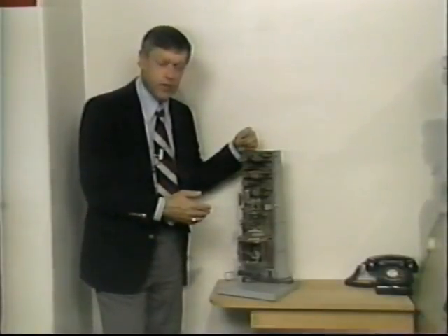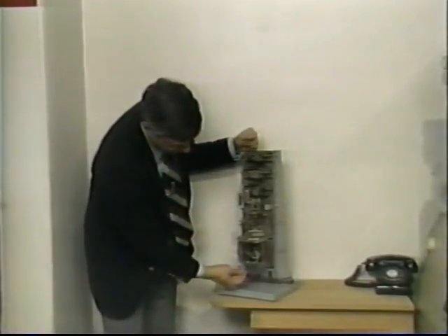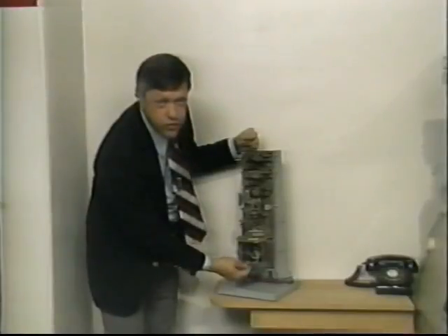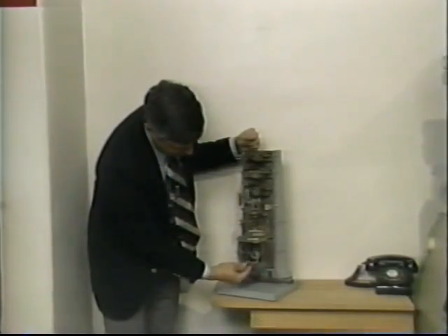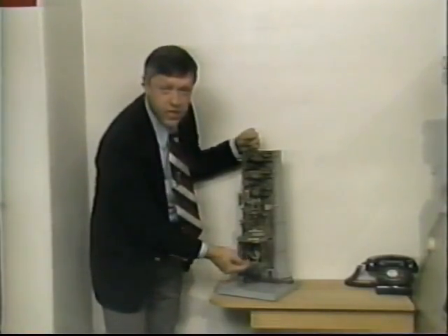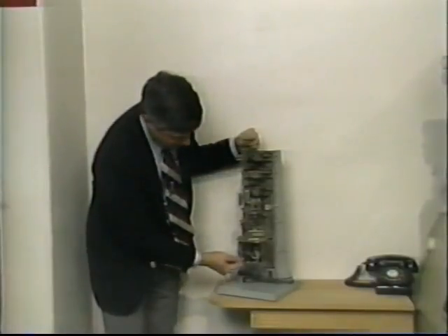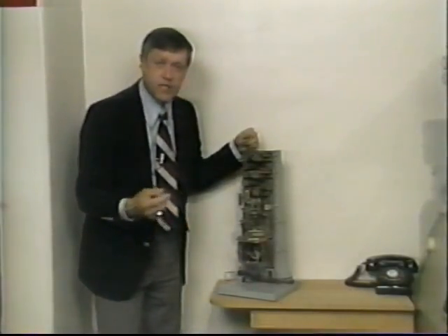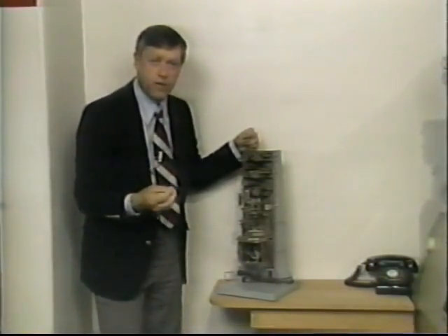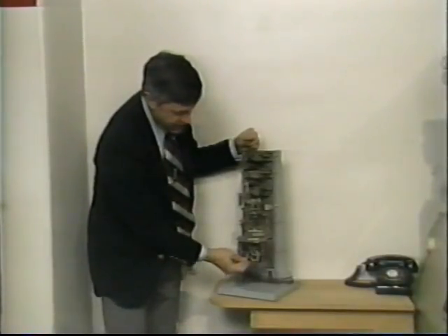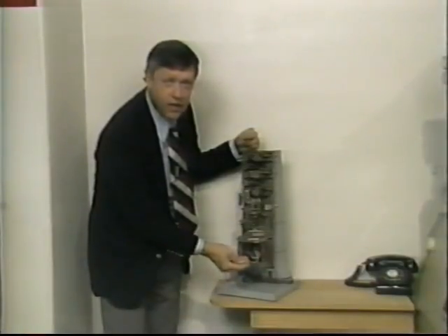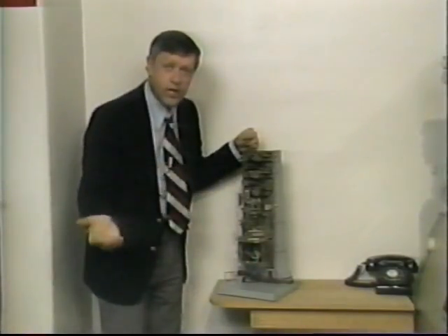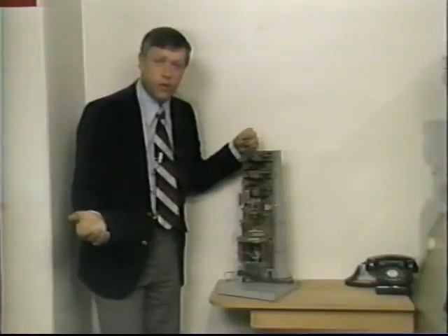This is what's called a stepper switch. Here are the electrical contacts which are actually going to connect the call. And what happens is the wipers here move up and down and rotate through the positions inside the stepper. Each of these electrical contacts inside could be connected to one telephone. There are 10 stages vertically on the stepper switch and 10 stages horizontally. So one switch could connect to 100 telephones.